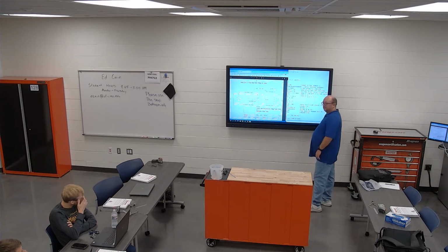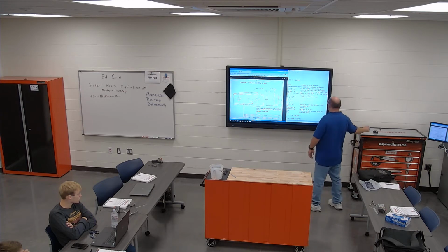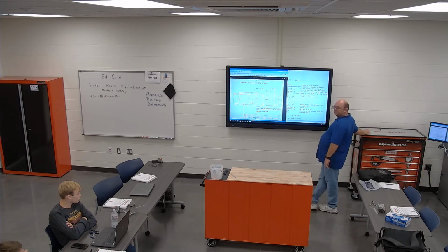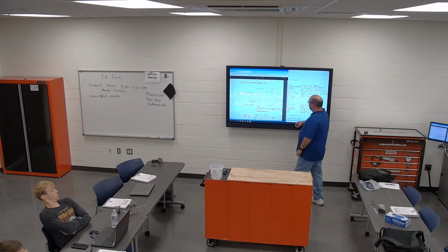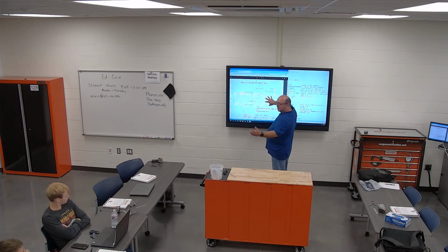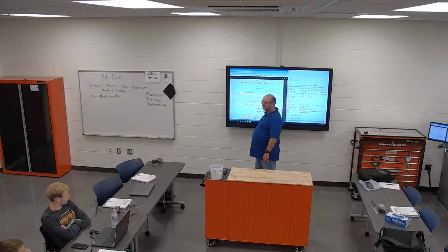Follow, John? No? You don't want your tool to start on top of your part in case you screw up your offsets, the tool can slam into your part. Does that make sense? So you bring it down inside your part right here, just like your programs usually do, right? And you face mill across and off and back up. Otherwise, you'll leave 2 different sets of swirl marks in your part too. Because you can literally mill to here and then pick up, but this is going to have a different finish than it does back here.